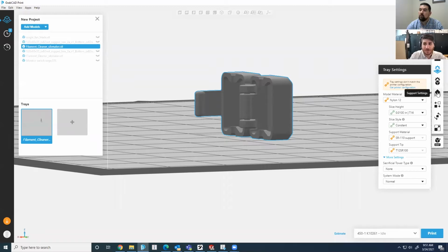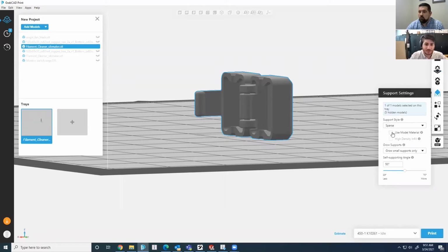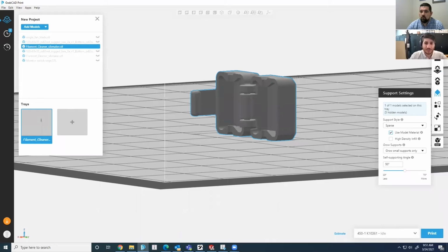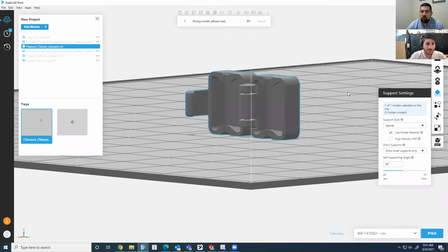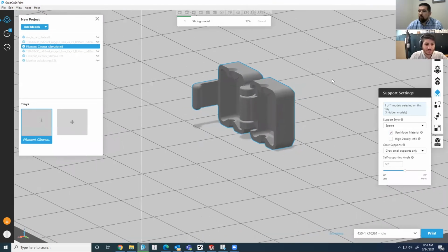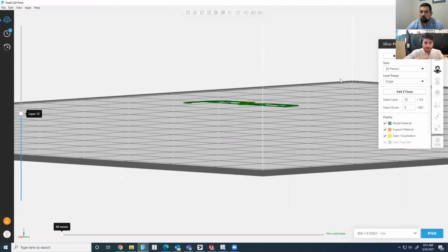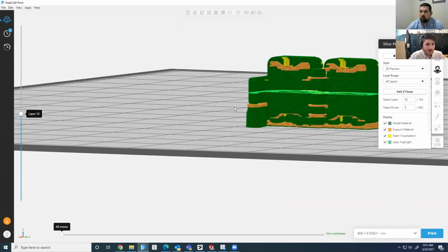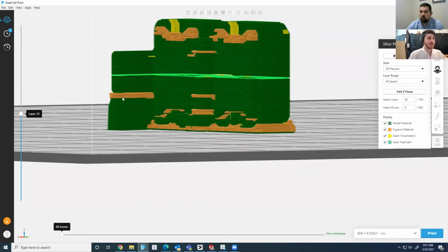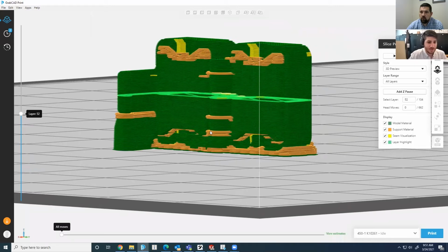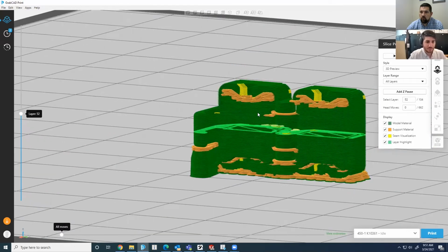What I like to do, and best practice when building in nylon 12, is to use model material where possible, as often as possible. That greatly reduces your curling and greatly improves your rate of success when printing in nylon 12. So again, having just these 4 layers of soluble support material underneath this arm, and having this model material being the same coefficient of thermal expansion, greatly reduces the risk of this failing, as well as it happening up here with the support material inside.